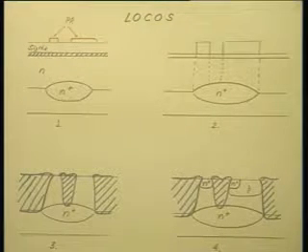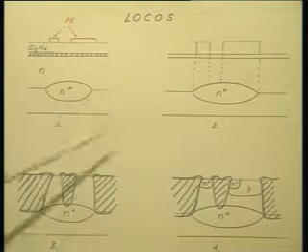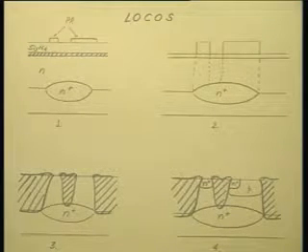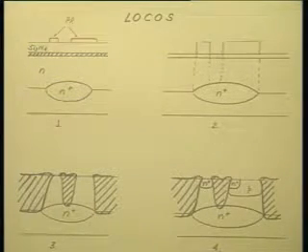Etching is done to realize only that much of recess, so that the top of the oxide comes only up to the surface. So, after this, when you carry out the oxidation, this is how the surface looks. You carry out the oxidation and then you remove silicon nitride from these remaining portions also.